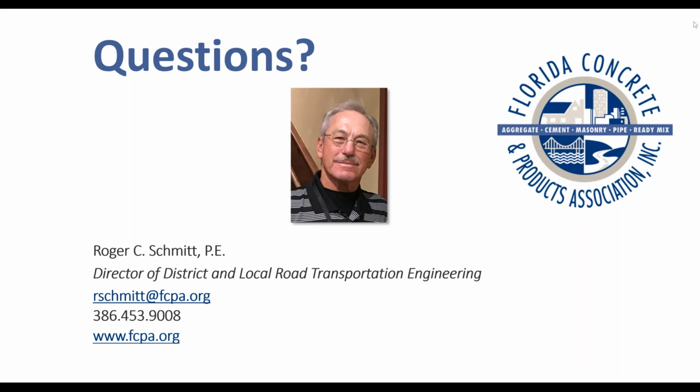so that you don't get the block cracking that could be a problem too. Another thing that they've done is that they like to limit the amount of cement that they use, because the least amount of cement that you can use that will help you the most is the one where it won't crack. So right now they're also getting some designs with less cement in it, so that it doesn't shrink as much. I hope that answers the question, but we've been discussing that with the DOT.